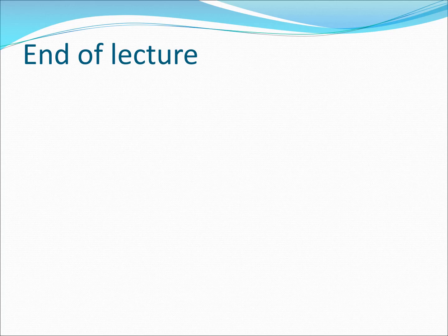And you never know what kind of loading will be there, which may sometime cause these stresses and strains to become larger. So in general, if you are dealing with real life problems, it may not be very useful to consider these particular plane stress and plane strain assumptions. But in case you are dealing with problems in class, in case you are dealing with problems for which quick solutions are required, you can do very well with plane stress and plane strain, because in that case you will get the solution very easily without resorting to all the cumbersome math which comes by dealing with the three-dimensional stress strain relationship.